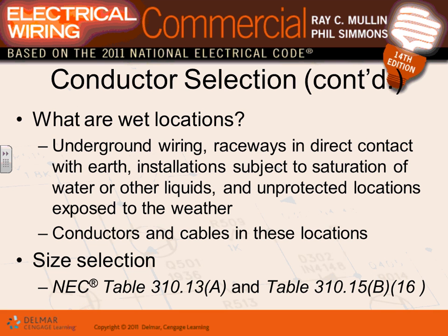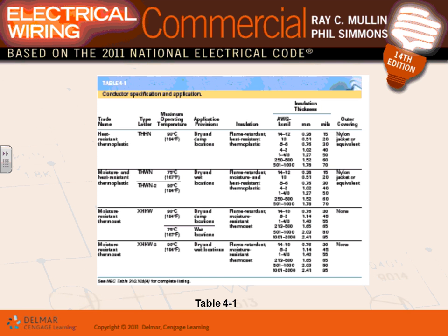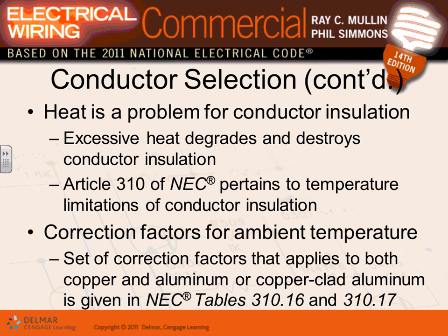We size them definitely based on 310.15(B)(16), as we have just done. I'll get into that one in a second. I always say when I talk about conductors, the enemy number one of electricity is heat. If you don't care about smoke coming out of the insulation of a conductor, you can make a number 14 carry 50 amps, right? You don't care about the insulation melting and smoking.